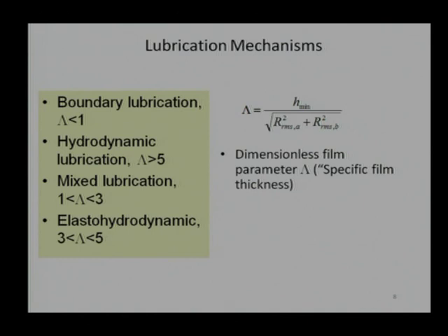In case of mixed lubrication, we use both the theories, boundary lubrication as well as hydrodynamic theory. Coming to the elastohydrodynamic lubrication, we use hydrodynamic lubrication as well as elastic deformation, and we need to make sure that the surface roughness is not coming into the picture. Otherwise, we need to analyze and find the elastohydrodynamic lubrication mechanism without asperity contacts.